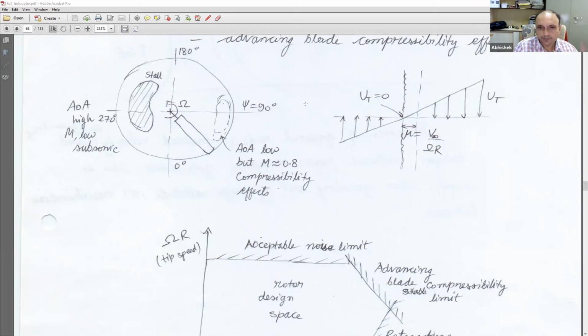But the challenge is that if I still try to fly like a helicopter by tilting and everything, my helicopter pitching forward and going, I will have a lot of drag. And rotors will not be able to give all the thrust because I have slowed them down anyhow. So in the Raider design, and also the larger version of the Raider, called Defiant, I actually put a propeller at the back and get the forward propulsion separately. So now this propeller at the back will allow me to fly as fast as I want. And my rotors are slower now, but they will still be generating enough lift to support the weight.